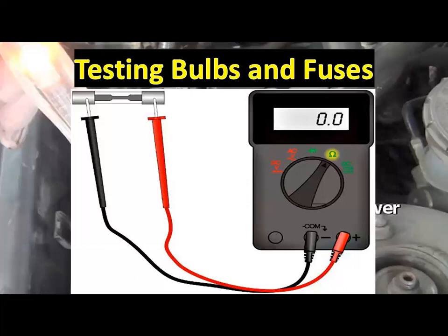Then headlights should be properly aimed vertically and horizontally. Digital ohmmeters do not require calibration. An ohmmeter may be damaged if it is connected to a circuit with voltage supplied to the circuit, so you have to select the DC volts. When an ohmmeter is connected to fuse terminals, a low reading indicates a satisfactory fuse. When an ohmmeter is connected across a filament in a bulb, an infinite reading indicates an open filament.